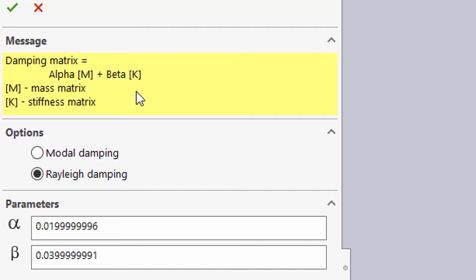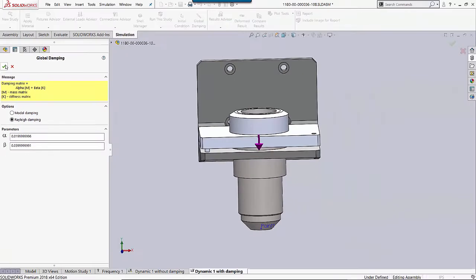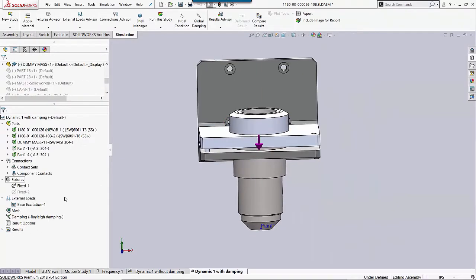Basically, it's saying that I've put this object into water or some other liquid, and that liquid is what is causing the dampening in this system. Complete Genomics didn't know at this time period exactly how their system will be dampened. They need to research that a little bit more. So because I don't know the actual dampening, that's why I chose to use Rayleigh dampening, which is the default alpha beta parameters.